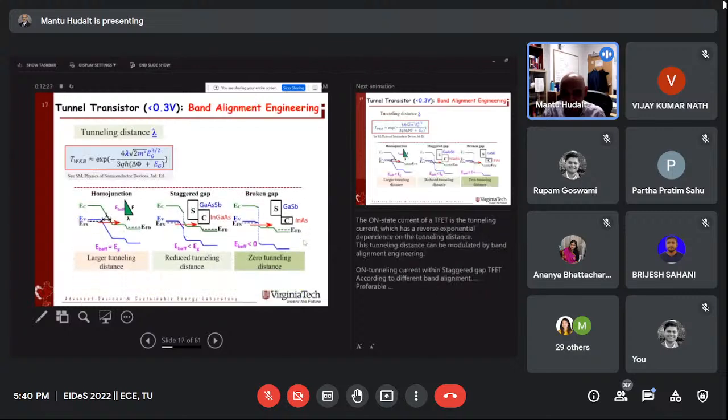Okay, basically then we see the last one, the middle one. What we are going to show is the material, now coming back to the material challenge. You see the EV effective, where S is the source, C is the channel, and the channel is InGaAs. Below the S is the valence band, above the C, which is the box where gallium arsenide antimonide is written, that's your conduction band. Think about it. Your carrier needs to go from the valence band of the source to the conduction band of your channel. So that's the staggered part.